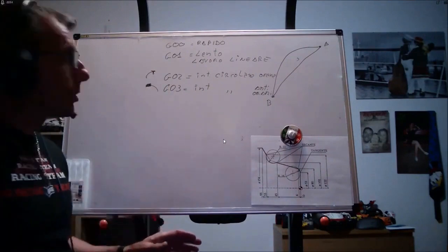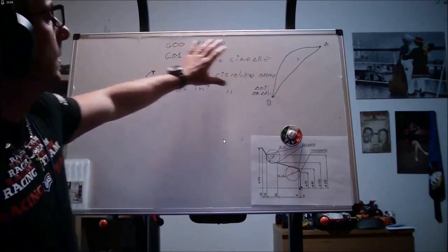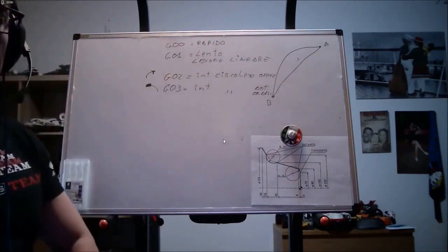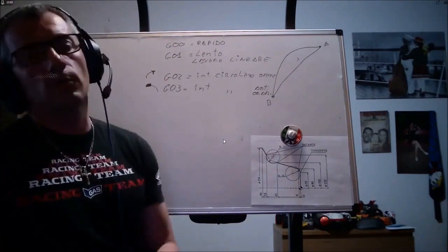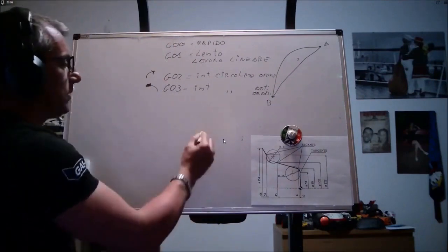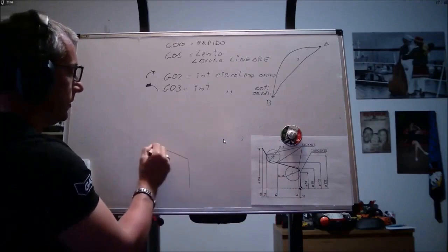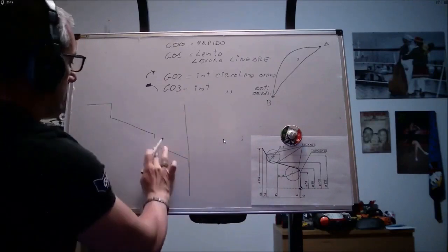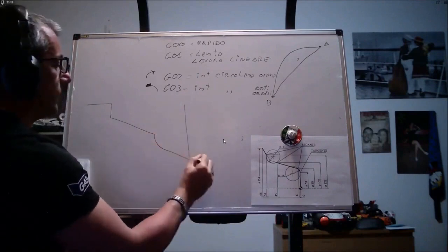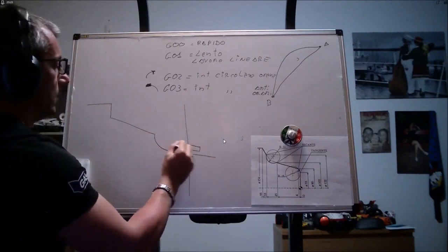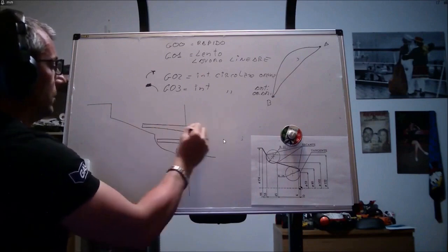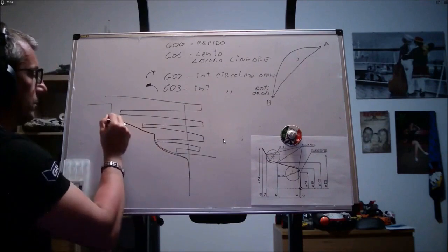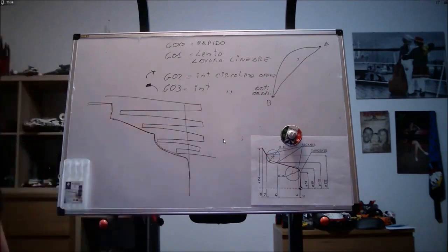So, good. With 4 codes, we can perform all the movements we want, excluding threading. We can already take a piece made like this and perform a facing, a roughing, because we only need G1, and a finishing using G1 and, in this case, G2.